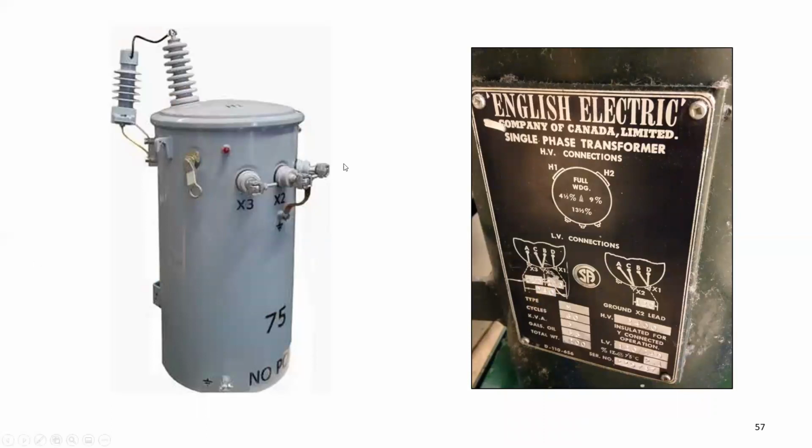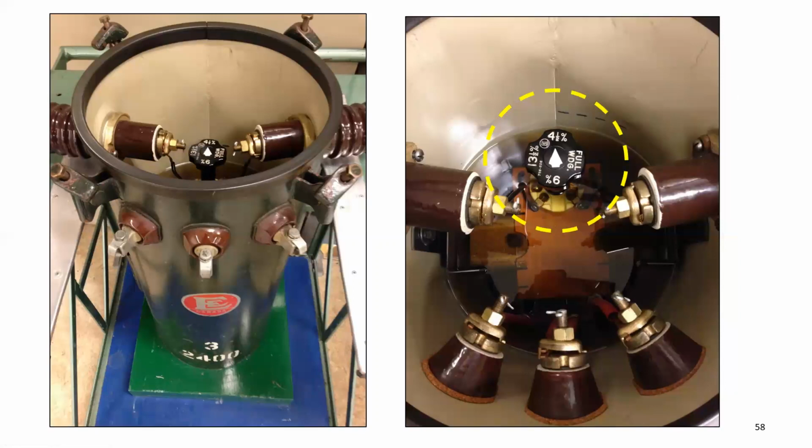Finally, we've got the same application on higher voltage transformers, and this is a single phase can type transformer. It's liquid filled and it's pole mounted. And this one, I've got a picture of a nameplate of another same type of transformer, just different color, and it has taps inside. It says 4.5%, 9%, 13.5%. And this one's set up in a little bit different manner in that the taps are located inside, but they're accessed through a rotating dial.